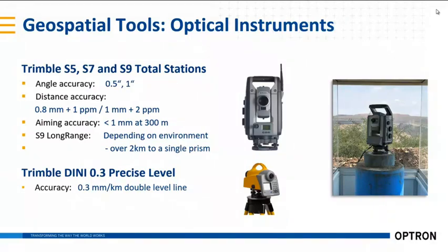I often say that a precise level is an extremely effective monitoring tool, because you can deploy it quite rapidly. It's quite easy to train up personnel in using it, and you can get millimeter results quite quickly. So it's a very cost-effective solution. So it's a very useful monitoring tool.